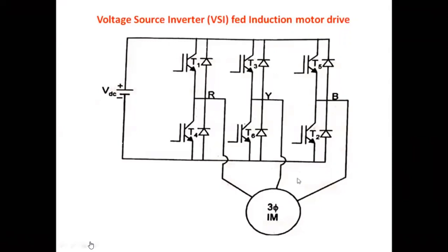Here my intention is to control the induction motor with variable voltage and variable frequency. These three terminals will act as variable voltage, variable frequency terminals. This is now achieved by using the VSI for the induction motor.